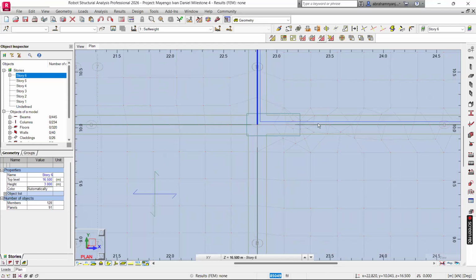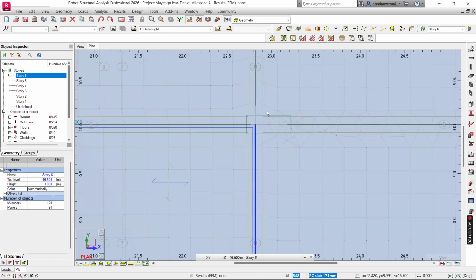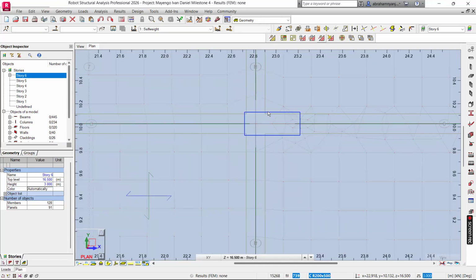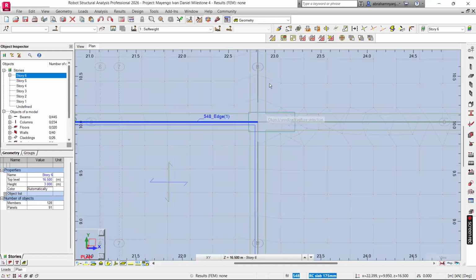What it means is that this beam should not stop anywhere, maybe along the face. You have to pull it and it also intersects at this point, meaning you're going to have beams that are intersecting at one point. So yes, the column positioning could affect your mesh. Still, if it was me and there are no constraints on any side, I would position this at the center so that it is loaded at its centroid.